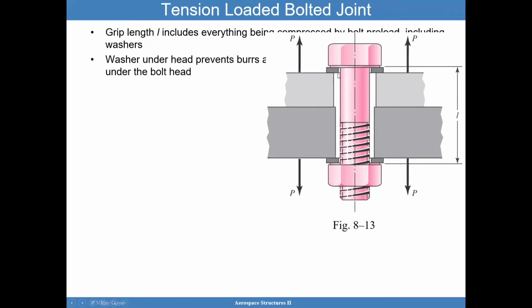The important thing is that tension loaded bolts are intended to compress the members and decrease the amount of bending that you may have in the system. Otherwise, if you have gapping, then the bolt has lost its purpose in this situation, which is to join two members together.